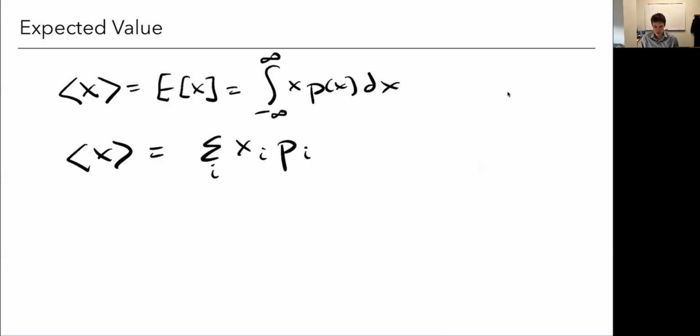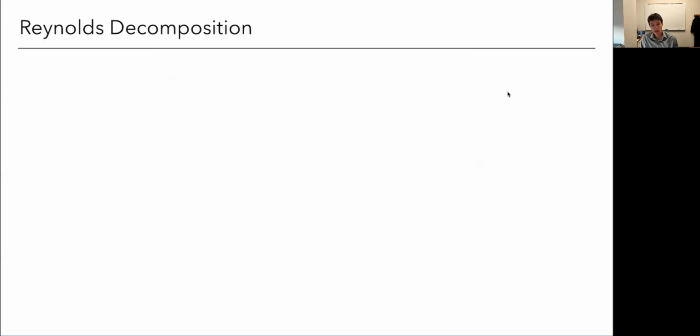Basic review. So the idea that we're going to use is what's called a Reynolds decomposition. So we're going to take all of these flow quantities that are of interest, the velocity, pressure, density, and so on, and we're going to just decompose it as follows. So for example, let's just take the x component of velocity u. We could say, well, that is equal to its average value, right? Because it's varying, let's say in time or in space, but in general it's varying, right?